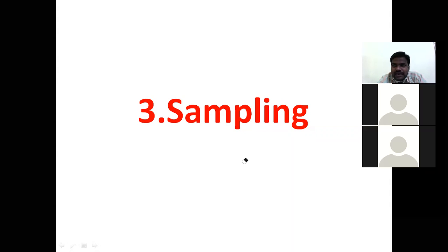Whenever you use the word digital or discrete, we have already seen the basic difference between digital signals and discrete signals. Discrete signals are also named digital signals if they are quantized in magnitude. What do you mean by quantization? Digital signal or discrete signal, both look the same, but where will we find the basic difference between these two? Discrete signals are termed digital signals once we take quantization in magnitude. Quantization is a process of rounding off or truncation of the digits.